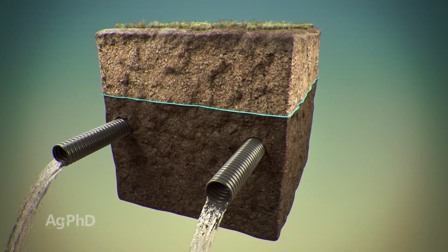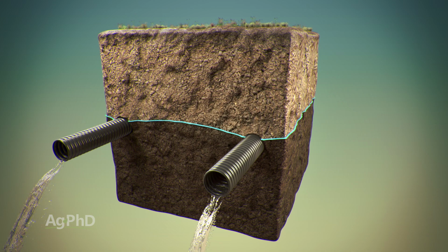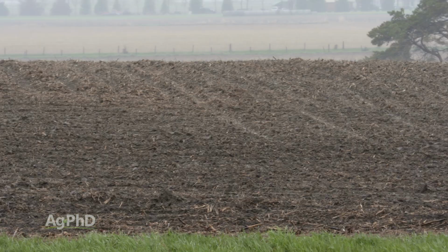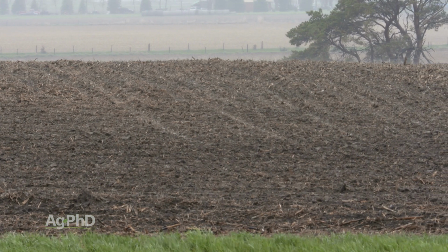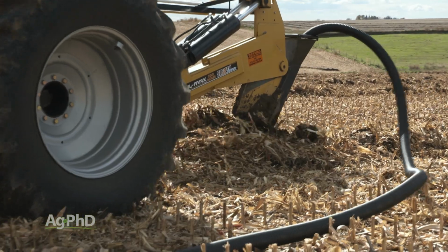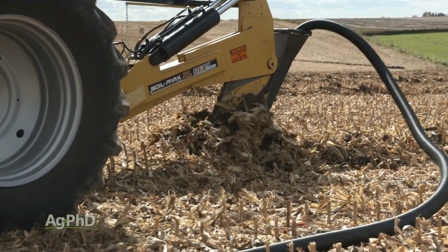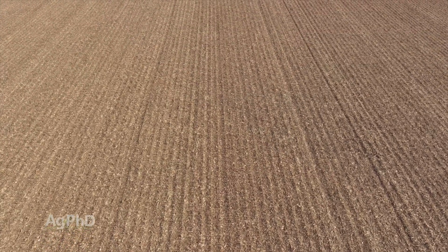So when you get those big rains, if you've got drain tile out in a field, it's already allowed the excess water to get away. So now that soil is like a sponge. It can fill back up again with that big rain as it comes. Studies have shown that tiling reduces erosion by 40 to 60%. Again, that's second only to going to very reduced tillage in terms of how best to reduce erosion out in a field.